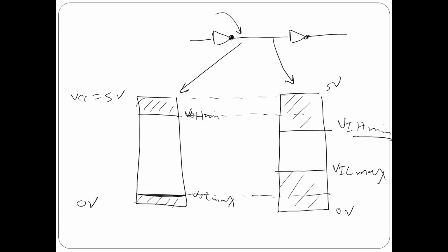Yes. So what happens if it's in between? That's a very good question. Because we are talking about transistors used like a switch, either open or closed, in order to do logic, the voltage has to be either in this range or this range, because we have either 0 or 1.